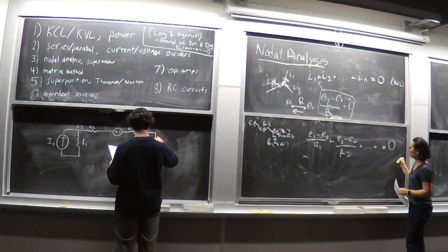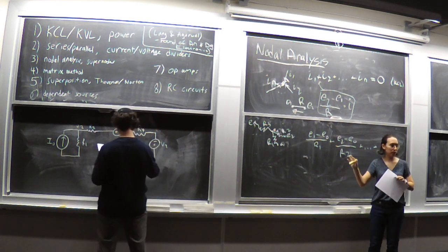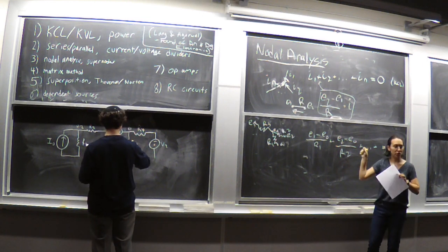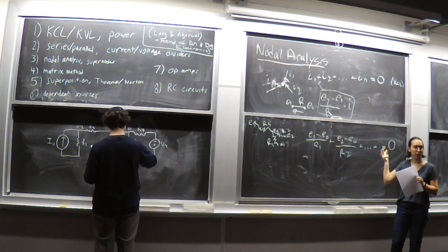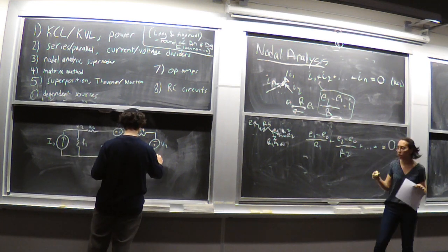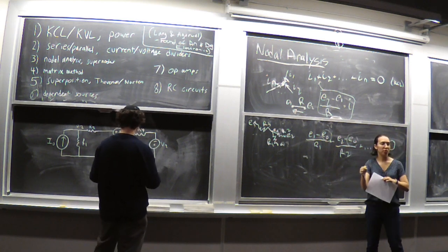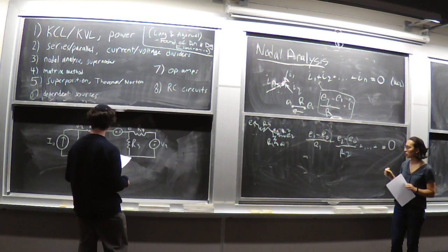And that whole sum is 0. So when you're going through your circuit, and we'll go through the formal steps of this, you'll pick each node, you'll write out the node equation for that node, and each node equation kind of has one special variable. So in this case, it would be E0, which is the center, the location you applied the node equation to.